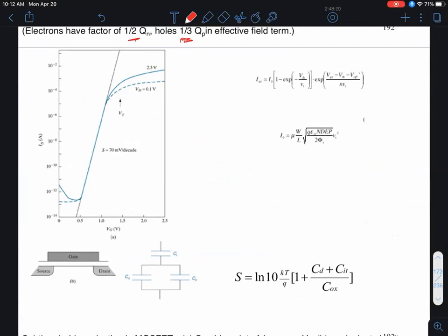The other thing that I hinted at is the so-called subthreshold characteristics or subthreshold slope. As I said, if you plot ID as a function of VG, you get this linear dependency going to 0 at VT, but in practice, current doesn't go to 0 right at VT, it'll slowly go to 0. This conduction below threshold is called subthreshold conductance, which is what I'm showing over here as a function of VG, but now not on a linear scale as before, but on a log linear scale. So I'm plotting log of the drain current as a function of the gate voltage.